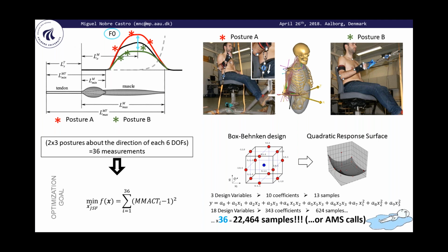And every time you do this, it typically takes 15 seconds for the inverse dynamic analysis to be ready, because you also need to remember to reassign the values for the tendon slack length and all those other variables that were previously defined.